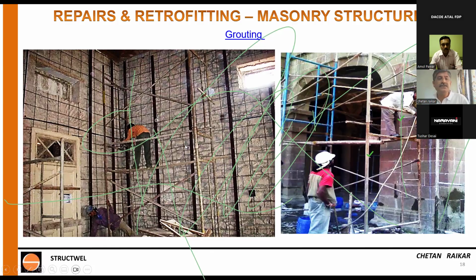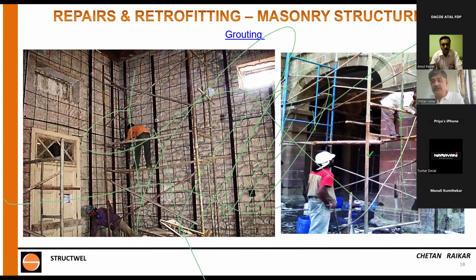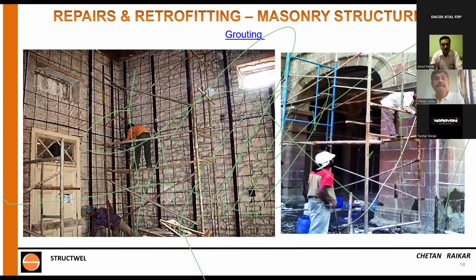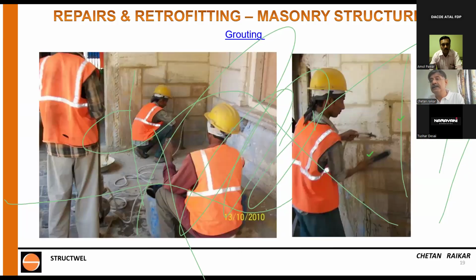This photograph does not show anything related to grouting, but this is where we had done the jacketing of stone masonry walls using guniting. We will talk about it when we go to the guniting section. You can see the reinforcement that is laid. This is another grouting done in an ashlar stone masonry. This is the same structure we saw last time, where we had used truck jacks to push the masonry and the crown stone back into its original position.